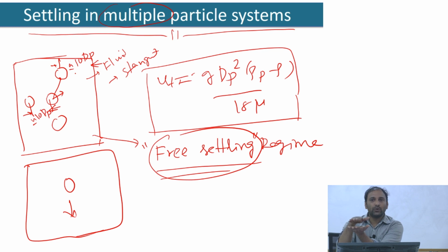There's a gap between two plates, for example, and one comes up with the question: what is the gap that I should maintain? Even in such cases, a typical rule of thumb is that the gap should be at least about 10 times the dimensions of the object that you have in the fluid.